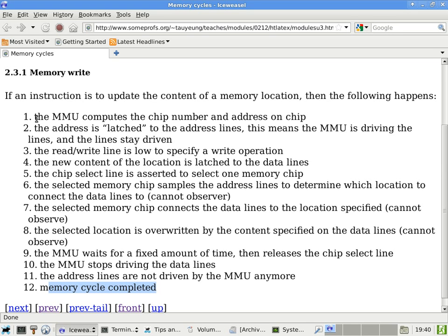And that's how DDR2 and DDR3 work. It is based on the assumption that you will also need the next so many locations. Might as well read all those locations at once, so you can save all the time to change the address line, to reassert the memory chip, and all the other stuff that is associated with this page.